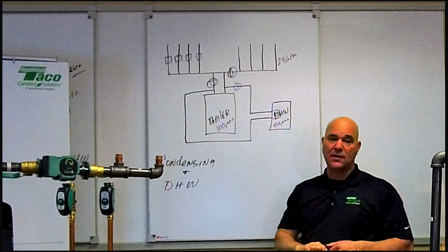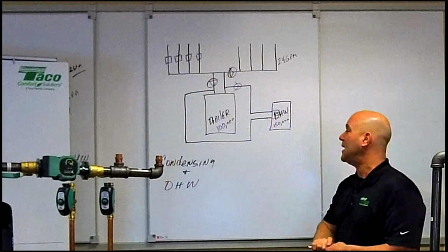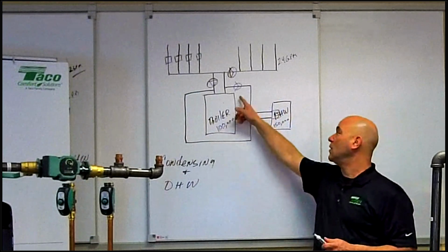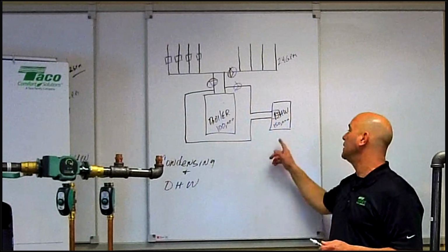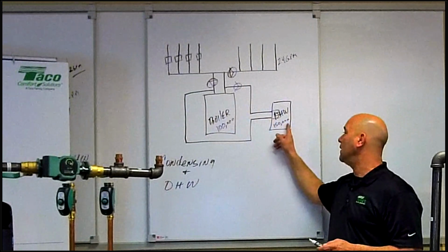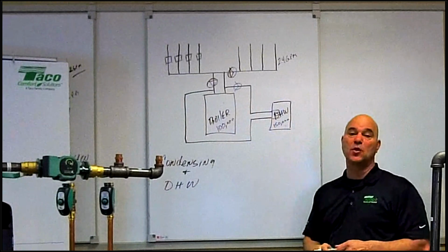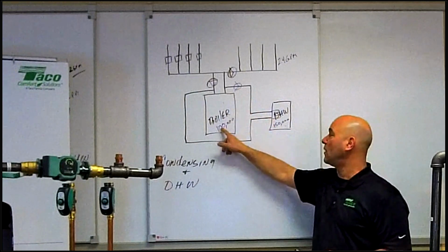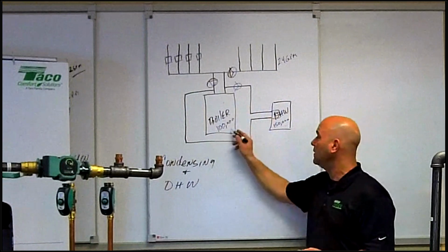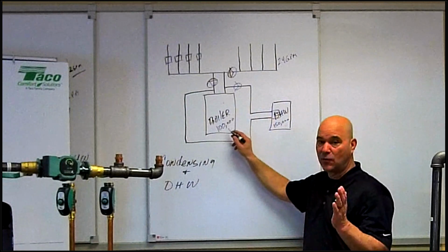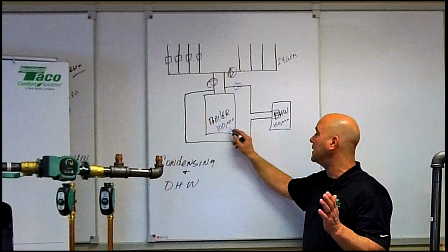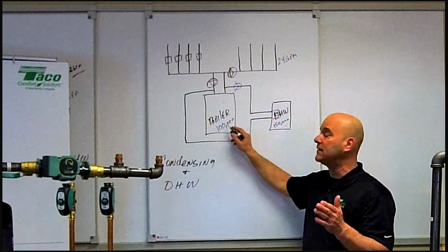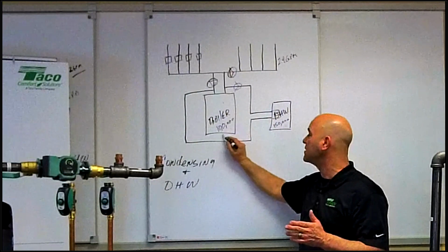But the real question I want to ask you guys is, I have a 100,000 BTU boiler. What am I doing here with this circulator when I have 150,000 BTU worth of absorption here in the indirect? Am I sizing this for 20-degree delta T? Remember, Universal Hydronic Formula, page 44, that TACO book, 20-degree delta T, Jim gave you the shortcut, take the comma, move it over one slot.